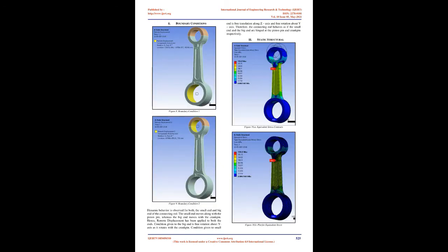A 2-piece con rod is made up of 2 parts to enable it to be clamped around the crank pin. The bottom part, or rod cap, is made of identical material as the rod and is fastened to the con rod by 2 bolts. The surface that is in contact with the crank pin is generally a split shell bearing. The 2 parts of the bearing are positioned in between the big end and crank pin by dowel pins. From the perspective of functionality, connecting rods must have the required rigidity at the lowest possible weight.